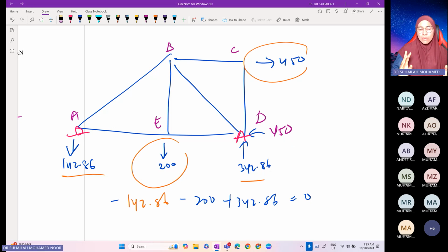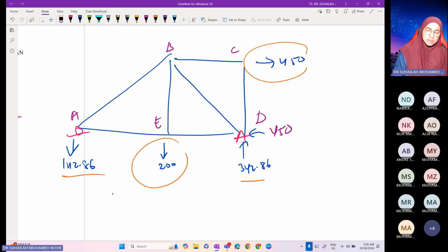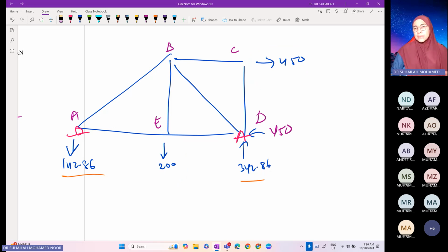But for AY and DY, we must take moment at A and moment at D, then apply the equilibrium equation, and we will get AY and DY. When checked for equilibrium, they also give zero, like what we checked. So for the truss, we must make sure it is in equilibrium first, and only then calculate the member forces in the internal system. All member forces are internal; from the external we get the internal, because every joint must balance.